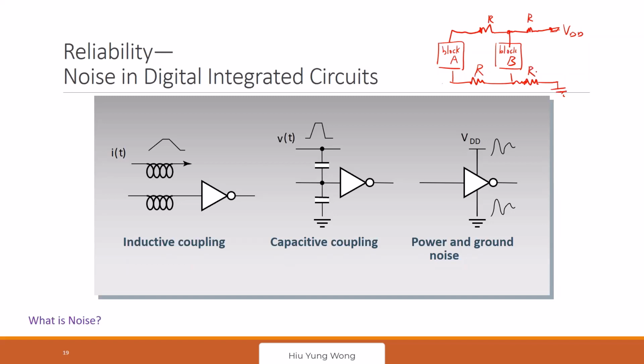So do not think that block A has the same reliability as block B. Even in steady state, you have the so-called IR drop. You don't really get VDD to your transistor. You're getting VDD minus IR. And you don't really get ground to your transistor. It's 0 plus IR. Okay? And then they have the noise coming from this source that can screw up your device.